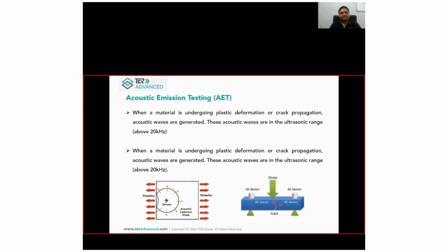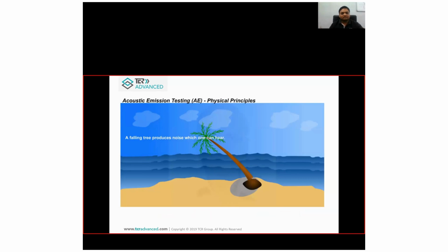To detect these active flaws, we mount the sensors on the entire pressure vessel, and we can test the entire component in one shot. This is the principle-related slide.